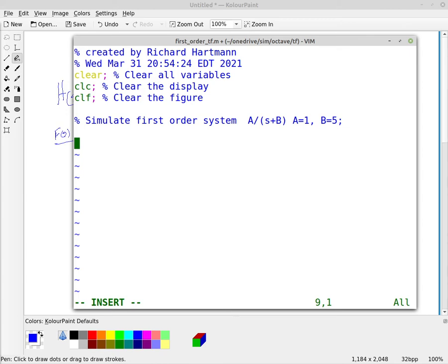And so again, the first thing we're going to do is set a time step. It seems like a pretty straightforward system, so I'll just use my standard 10 millisecond time step, and then I'm going to create my time vector starting from 0 using my time step. I'm not quite sure how long to run it, so I'm just going to start with 3 seconds and we'll see where we're at and make adjustments from there. And remember, transfer functions basically state that the system starts at 0, so I'm going to initialize my x equal to 0.